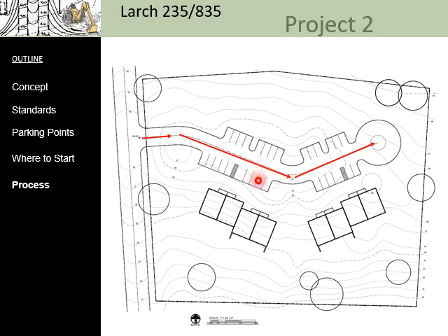Once you have that figured out in one spot, that same information can be duplicated very easily. So for example, if you found that this was an elevation of say 28, which it could not be on this plan, but that's not the point. If this was an elevation of 28 and this wound up being an elevation at say 30, you could then go and do the same thing by simply adding 2 feet on every one of these. And again, I'm just using that as an example. I'm not saying that is the answer, but my point is, once you do one of these, do not waste your time calculating everyone individually because you are still in the concept phase.